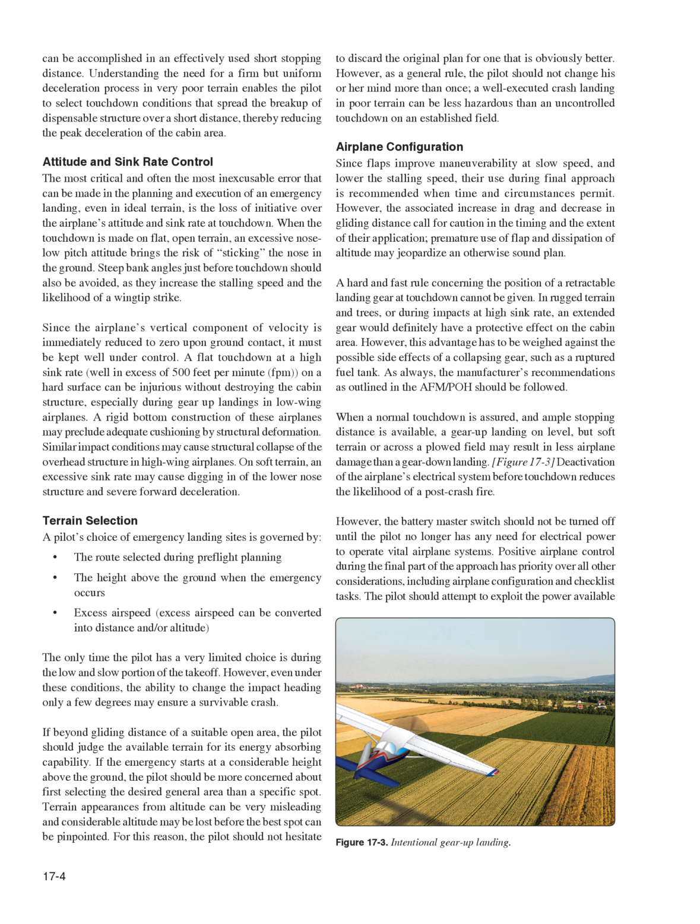Attitude and sink rate control. The most critical and often the most inexcusable error that can be made in the planning and execution of an emergency landing, even in ideal terrain, is the loss of initiative over the airplane's attitude and sink rate at touchdown. When the touchdown is made on flat, open terrain, an excessive nose-low pitch attitude brings the risk of sticking the nose in the ground. Steep bank angles just before touchdown should also be avoided, as they increase the stalling speed and the likelihood of a wingtip strike.